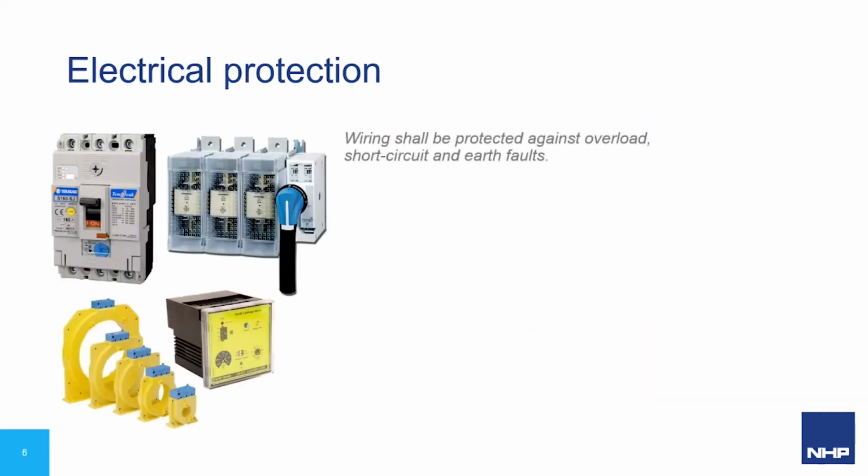So section 7 states that electrical circuits and equipment shall be protected against overload, short circuit, and earth faults with the dangerous effects that these have on equipment, which of course is only made more dangerous within the case of hazardous area environments due to the heating acting as a potential source of ignition. Now, it details that you must use overload protection for electrical equipment if an overload can occur to the electrical equipment and the avoidance of this can't be guaranteed.